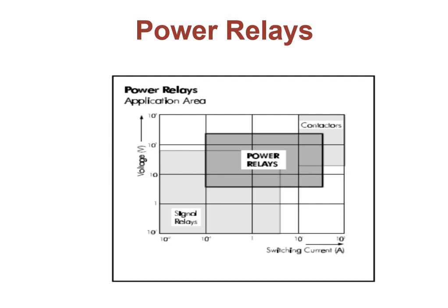Then contactors. Although contactors are not strictly relays, they have the same design principles. Like relays, they are remote controlled switches. The difference is the considerably higher input power consumption, higher switching capacity, and larger size.